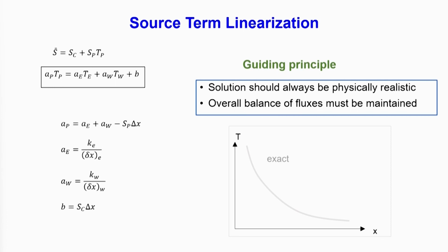You can take the source term as any arbitrary function of temperature, as in the profile assumption, but the finite volume method gives a flexibility of taking the source term's dependence on temperature in a manner which is different from any other temperature variation that you have taken for other terms. So, you do not have to take the same approximating function for all the terms, that flexibility you have. The reason is that this is only for the integration, and once that integration is done, its history of how the integration was done may be lost, that is not important.